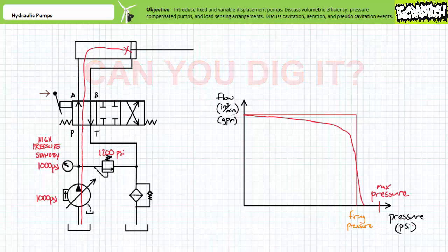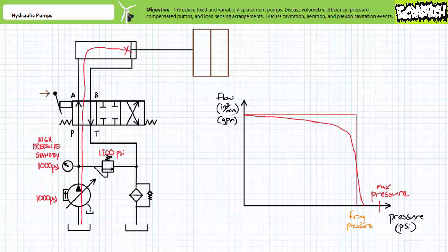In both scenarios, the closed center and when the actuator reached the limits of travel, pressure rose to the firing pressure and the pressure-compensated variable displacement pump simply destroked to 0 gallons per minute and stopped pumping when the circuit didn't need it. A pressure-compensated variable displacement pump can be used for applications necessitating an actuator extend with a given force and then maintain that force for a lengthy stall period. For example, a cylinder used to compress a mold.